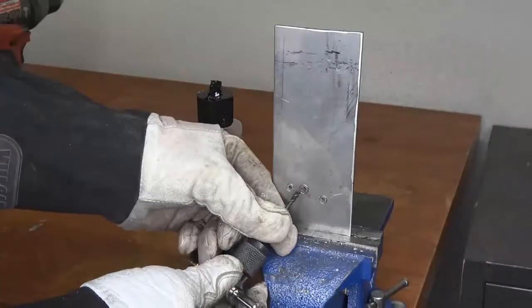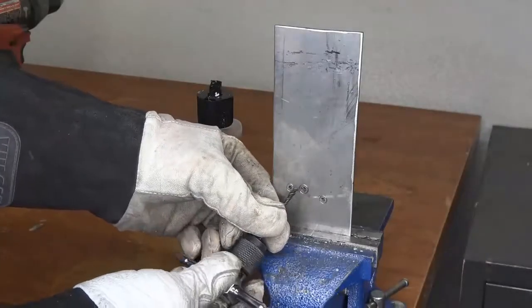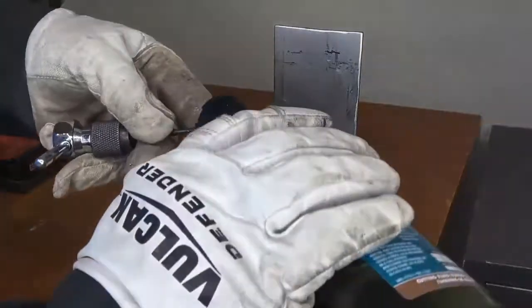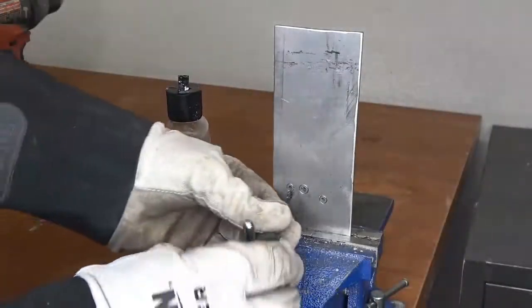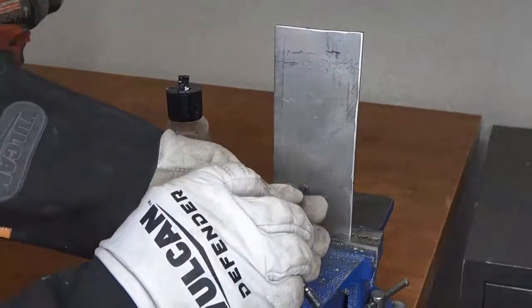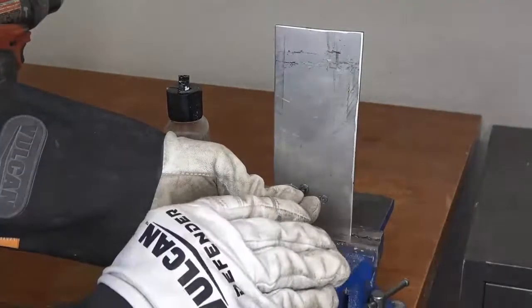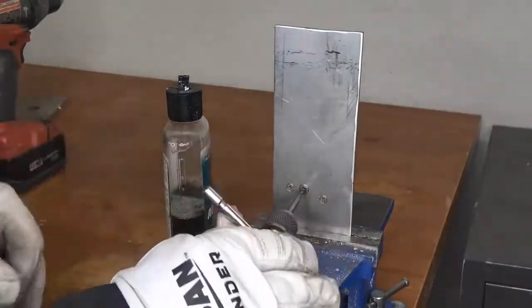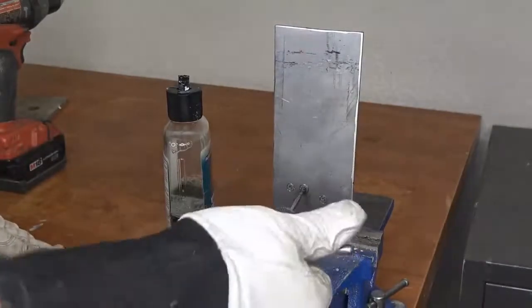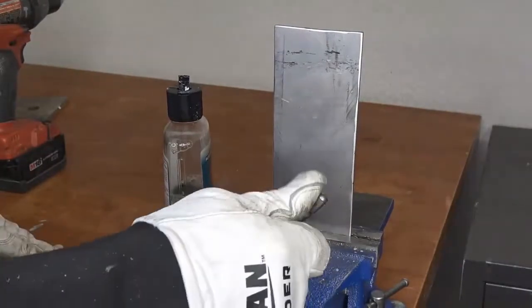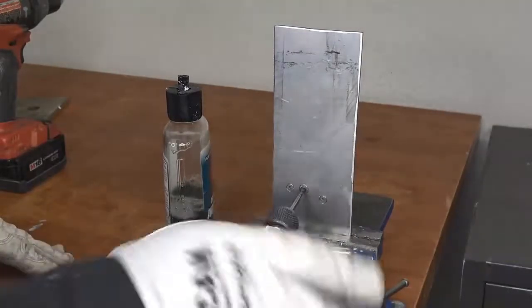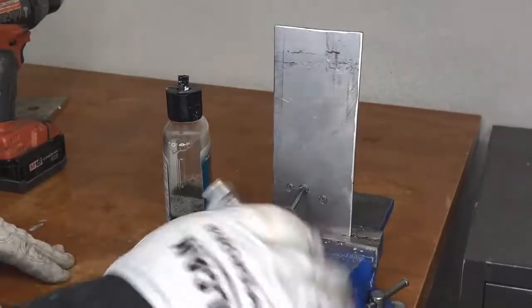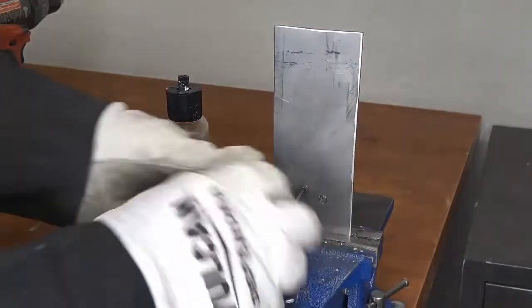And if we're doing a really tough material like stainless steel, this is a plate of 1/8 inch steel, 3/16 marine grade stainless, and that spiral flute tap just makes quick work of it. Does a good job of cleaning the chips. Chips are the little pieces of metal that are coming off of it, and it just makes for a good day.